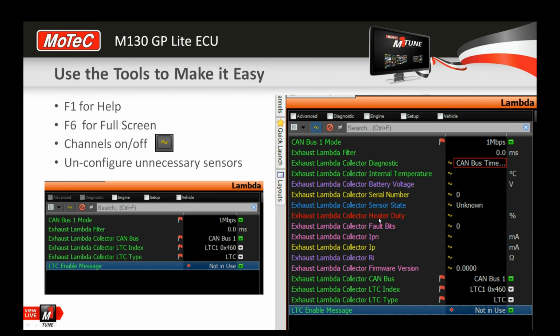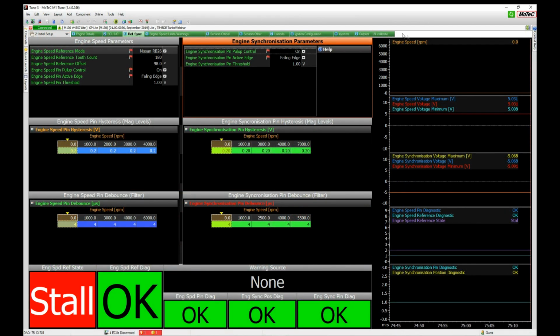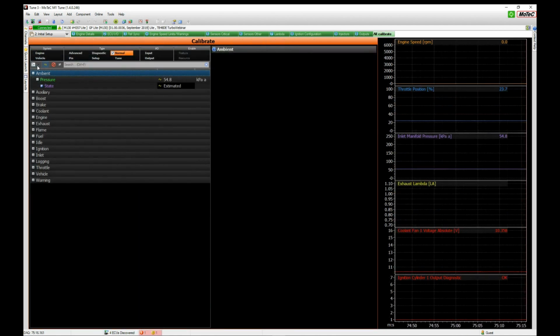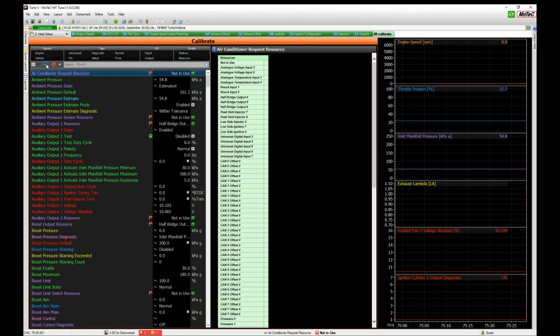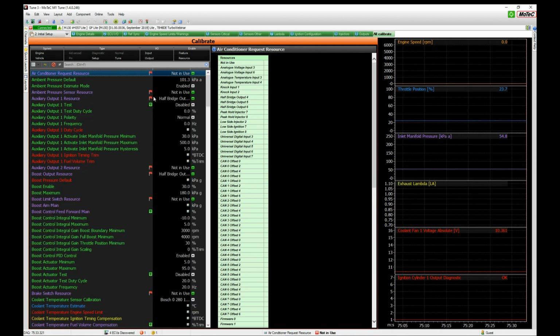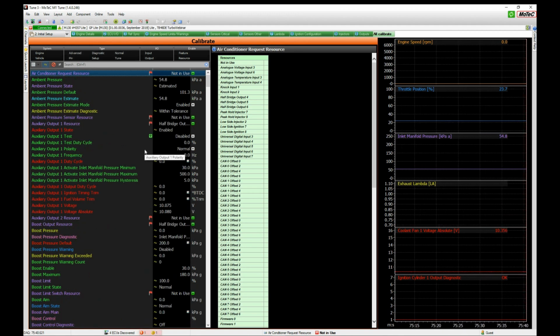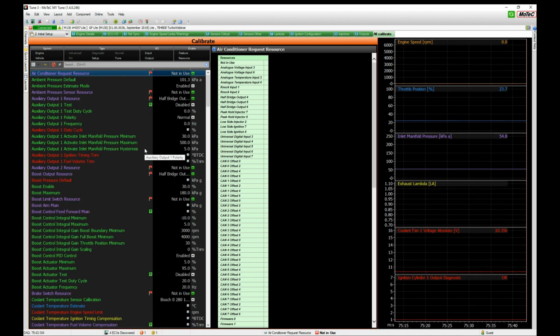Let me have a look for you. Okay, so if I go to all calibrate, I can switch to list view. Right, you can see all these channels here. They're not a table or a parameter or anything like that. These are just channels. So I can click them on and off here. Alright, see they're gone, and now with them gone I just have either tables or parameters to view. Alright, and Shift C. Yeah, Shift C is the shortcut for that. Okay.